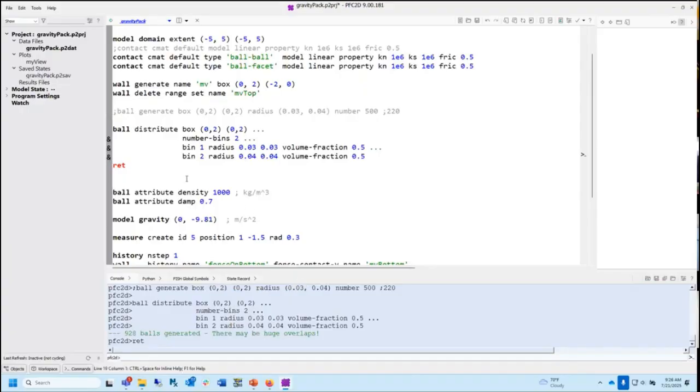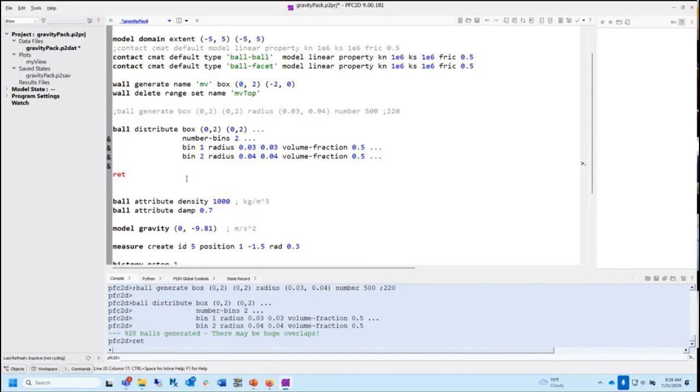Okay. And this is because there's one other thing here we need to talk about, and this is the thing I didn't give. Think of it this way. I'm telling it to use particles. Half of the volume has this size and the other half has that size. That's fine. But I didn't really tell it how many particles, right? I mean, this is a size distribution, but I could make 10 trillion of them that satisfy that, or I could make 17, right?